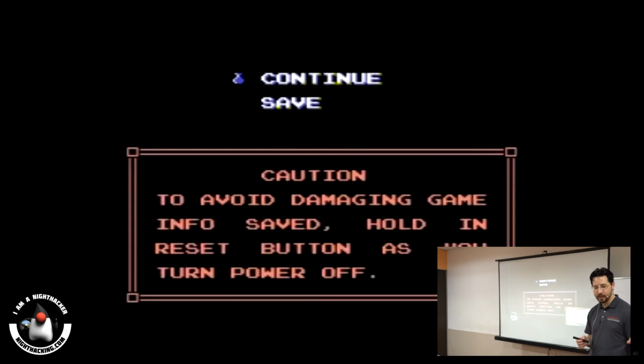But really, this type of manufacturing is designed for... That kind of case manufacturers are not available, so you printed on your own. Yeah. So this is best for things which you're prototyping during the design phase. Once you've finished and it's ready for production, if you want to print thousands of these, what you would do is give this to a company which would make a mold out of it. They'd turn it into an injection mold, and the injection mold itself is going to cost a few $1,000s to build a proper mold. But then once you do that, you can quickly manufacture a lot of units for pennies. 3D printers are best for prototyping though, because you wouldn't pay the cost of building an injection mold just for one trial.